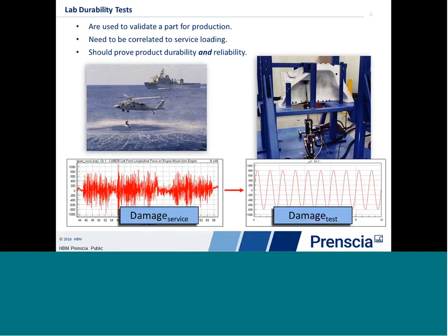And the way we do that is by testing not just one sample for one life. Maybe we test multiple samples for longer times, or a few samples for a much longer time, and we use that to infer characteristics of life for the population. And that allows us to meet, say, warranty targets and life and reliability and so on, those metrics.